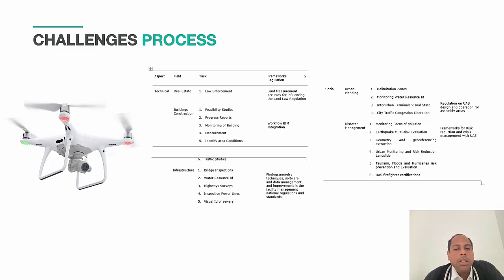In urban planning, it's more about safety. If you fly in a congested area, just make sure that radio frequency is okay, and check regulations regarding the design and also the operation. If a drone weighs more than 2 kilograms, you should have different safety measures to mitigate problems if the drone fails or something happens.